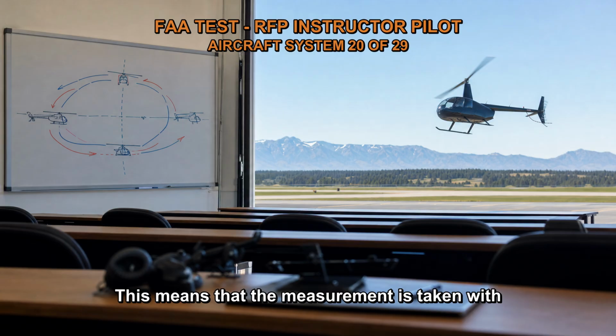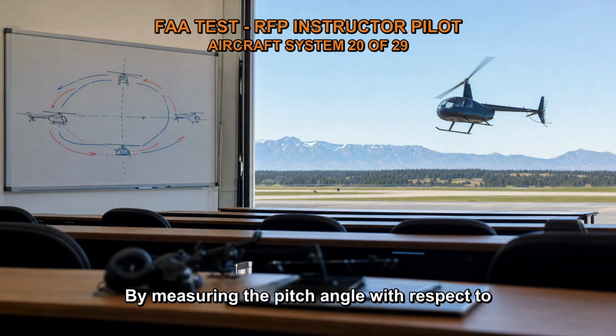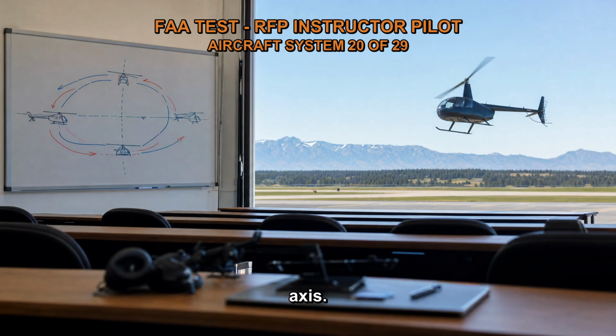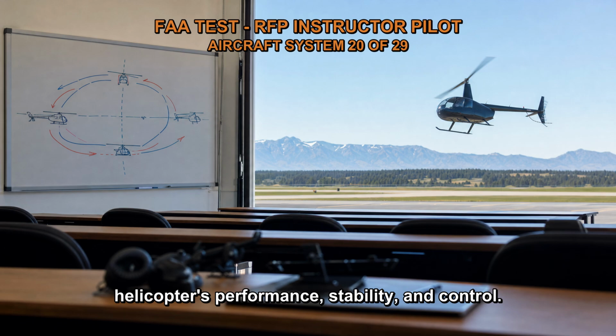This means that the measurement is taken with respect to the fixed reference plane formed by the rotor's rotation. The chord line serves as a reference for determining the pitch angle. By measuring the pitch angle with respect to the rotor plane of rotation, we can accurately describe the tilt or angle at which the rotor blades are set relative to the rotational axis. This angle determines the amount of lift and thrust generated by the rotor and affects the helicopter's performance, stability, and control.